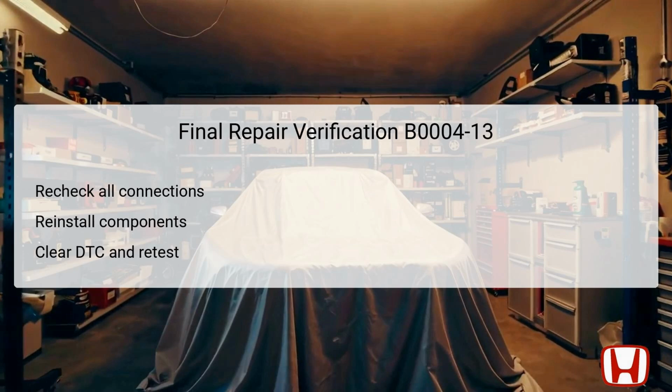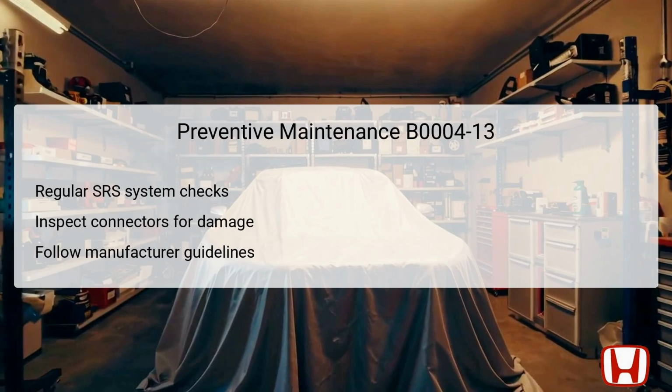Subsequently, perform a retest by turning the ignition to the on mode and monitoring for any reoccurrence of DTC B0004-13. This verification step helps ensure that the repair efforts were successful and that the airbag system will operate correctly during an actual incident. To prevent future occurrences of DTC B0004-13, implementing regular preventive maintenance processes is essential.